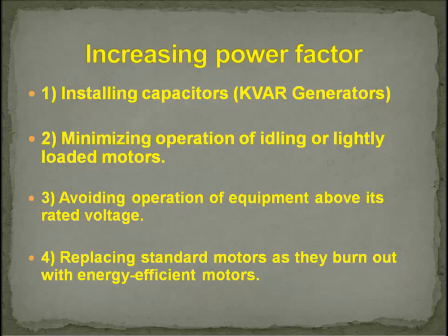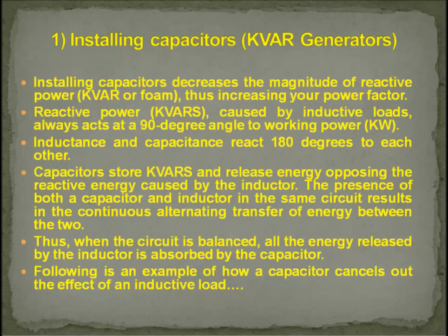Ways to increase power factor: 1. Installing capacitors, kVAR generators. 2. Minimizing operation of idling or lightly loaded motors. 3. Avoiding operation of equipment above its rated voltage. 4. Replacing standard motors as they burn out with energy-efficient motors. 1. Installing capacitors, kVAR generators.